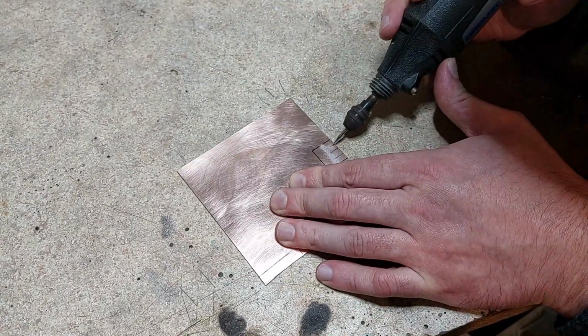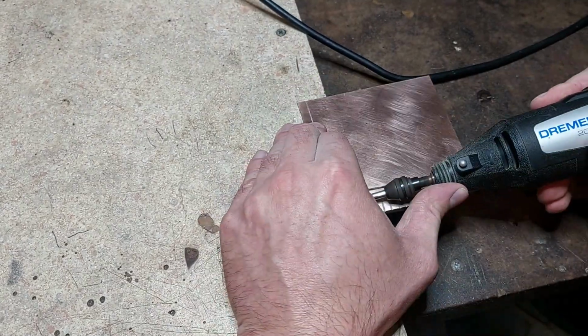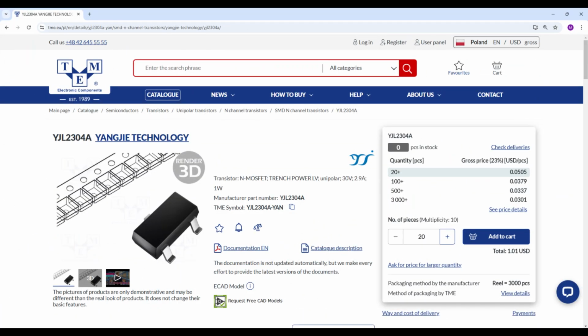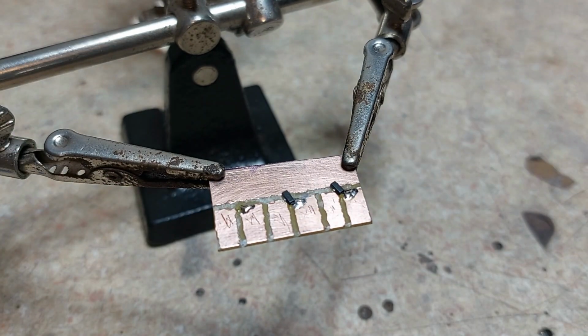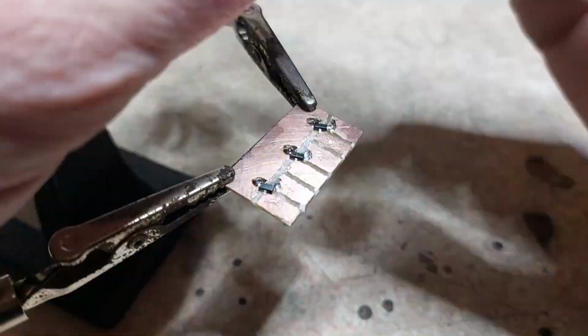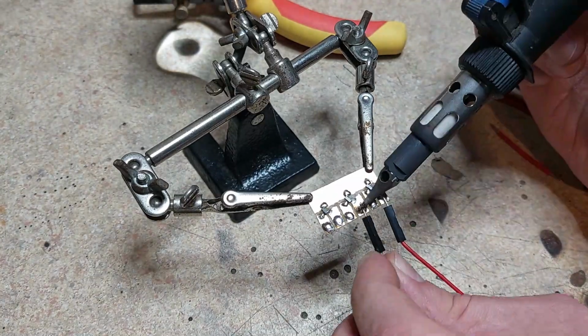But if doing some sort of soldering yourself is not an issue, you can prepare a piece of PCB, for example like this, and use this model for just few cents. This way you can make a power module for any number of channels you want to use, while keeping it small and affordable. Really nice feature, especially when dealing with RGB strips that require 3 lines per strip.